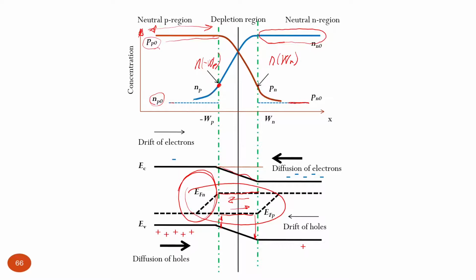the current-voltage characteristic for the case of dominant charge transport, which is recombination via a deep energy level within the depletion region, then it's necessary to calculate this profile of charge carrier concentration inside the depletion region. We will talk about this a little bit when we have already discussed the ideality coefficient of the current-voltage characteristic, but definitely it goes beyond the scope which we are going to consider in this course.